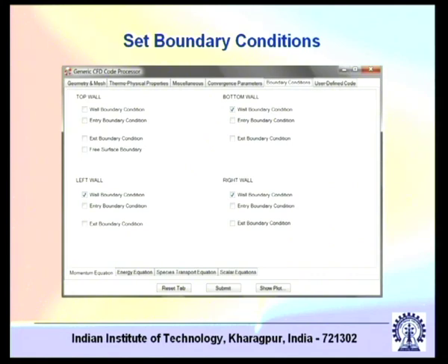The outflow boundary condition or the exit boundary condition is where you specify that along the stream the gradient of the variable is equal to 0. So for example if it is a fully developed flow, the outflow boundary condition is that along x there is no further change in u, so del u del x equal to 0.